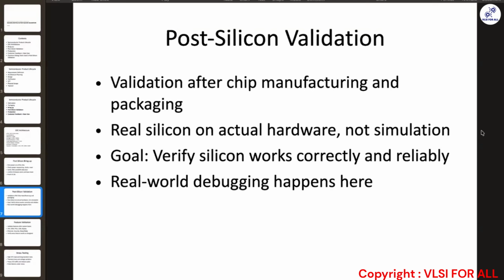You check whether the display is coming up along with other display adapters in the device manager, whether enumeration is coming up or not. So this is one test case. Your display is coming up or not, what resolution it has, whether it is working at the expected refresh rate or not. All of these things you check in the post silicon validation.